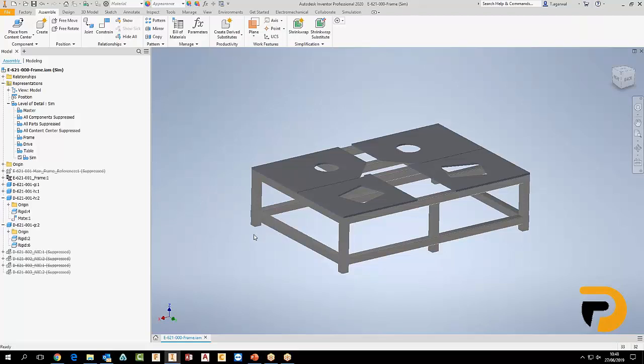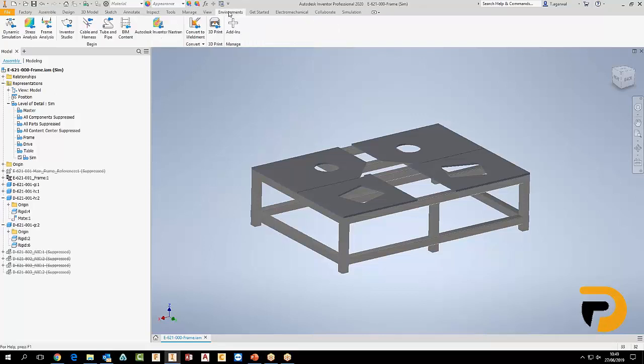Contacts are critical in your simulation studies. If your contacts are not set up correctly, you're not going to have an accurate result. You're not going to get the true behavior of a design in an FEA environment. Definitely. So as a big part of your workflow, contacts are huge. Not only your constraints, not only your loading, but contacts will have to be looked at. Yep. And there's certain criteria we can work on to get that. You can do automatic contacts, where we make assumptions, but it's possibly not the ideal workflow. I prefer to use manual contacts. Definitely. Again, it may cause a bit more work up front, but at the same time you get a more true representation. Accurate results, that's about it.